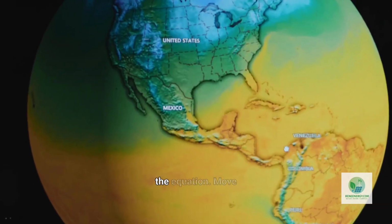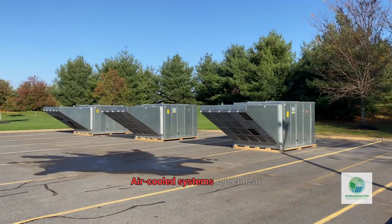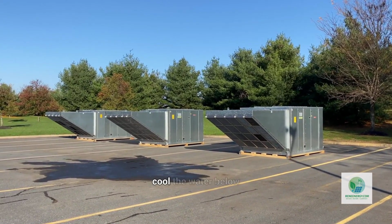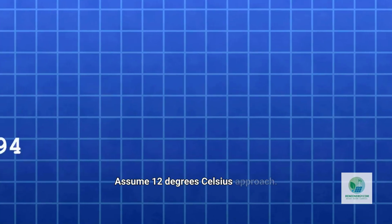Now climate enters the equation. Move to image number 5. Image number 5 shows a dry cooling system operating in a desert environment. Let's assume we are designing a plant in Abu Dhabi with a design ambient temperature of 50 degrees Celsius. Air-cooled systems reject heat to the ambient dry bulb temperature. But they cannot cool the water below that temperature. In fact, they require an approach temperature difference. Assume 12 degrees Celsius approach.